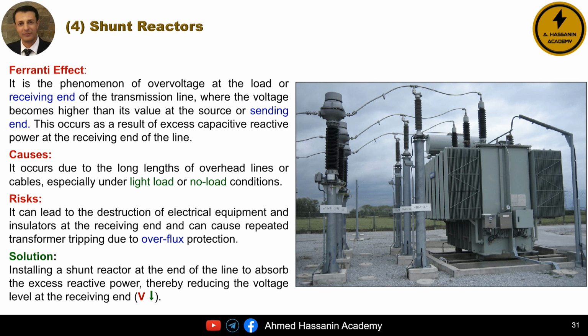The main issue here is that it is technically unacceptable to keep the shunt reactors permanently and continuously connected under all operating conditions. This means that there is a need to repeatedly connect or disconnect the shunt reactors depending on the variations in load.